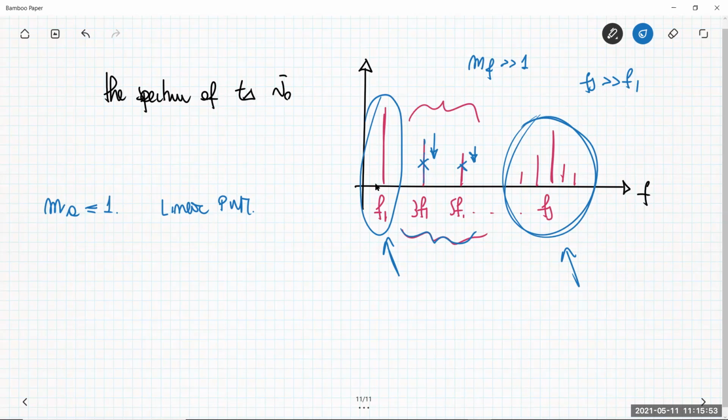It is a translation of the way I can communicate my information. The information which is within the amplitude variation or the frequency variation of the control voltage now becomes a variation of the pulse width, the pulse width modulator duty cycle, basically, that changes according to the sine wave variation of the control voltage. So I'm using this translation in order to drive my full bridge.